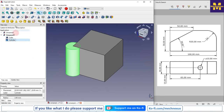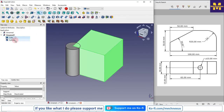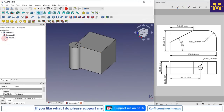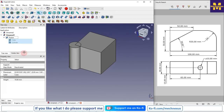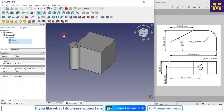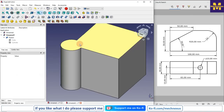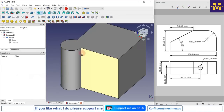And then we will select the cube and cylinder again and click on this union option. Here the material has been combined, but still we are seeing the edges here. If you want to hide the edges, then go to the property view, click on the fusion, and here in Refine, where it is false, select true. So now it seems to be perfectly combined.